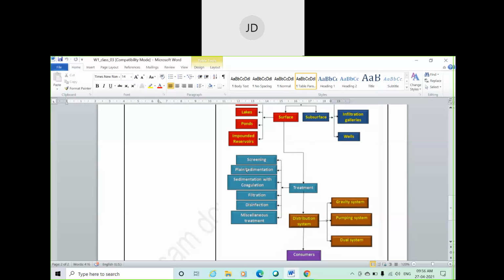To make them settle in the tank and separate from the water, we have to go for coagulation and flocculation. As a basic summary of this part, we add a coagulant or flocculant, like alum; different chemicals can be used. This chemical makes flocs, forming a film around the sediment or impurity, so the impurities stick with each other, become heavy, and finally settle in the coagulation and flocculation tank. I'll not go into very much detail; you can find it in your previous class notes.